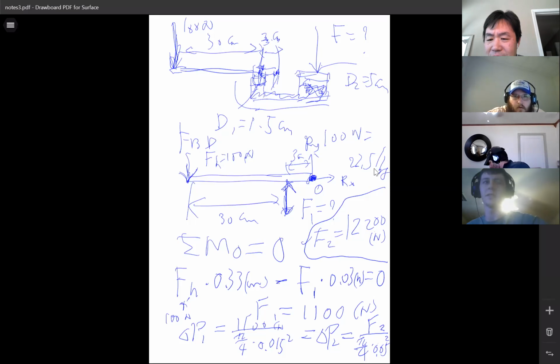It's about a fluid: you're adding some pressure to a certain point in the fluid. This is the hydraulic jack example we had last time. What happens to the pressure that you added? Everywhere gets the pressure equally. The pressure added to the fluid system will be transmitted freely, 100%, to the entire fluid. So everywhere will feel the same added pressure.